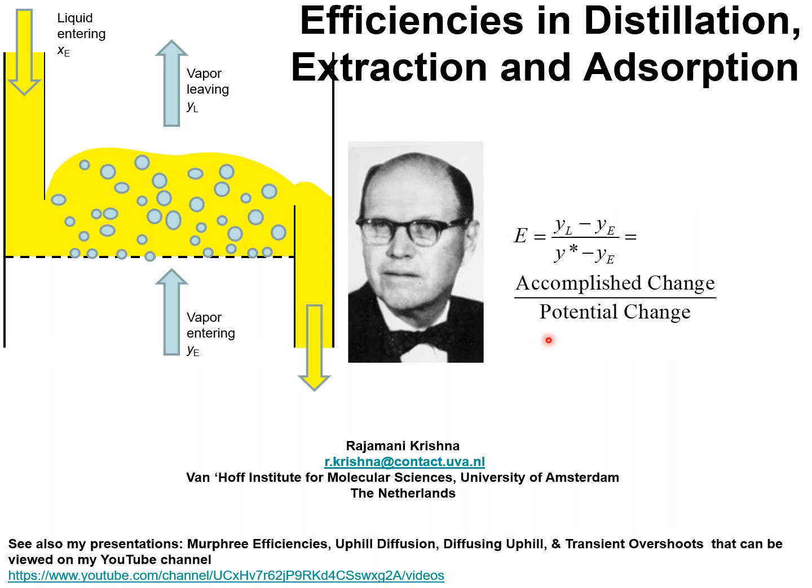In this presentation, I would like to demonstrate, firstly, that the component Murphree efficiencies for multi-component distillation are indeed unbounded and can have component efficiencies greater than unity or less than 0.